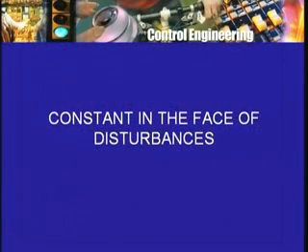So this will remind you of what we talked about earlier, trying to keep something constant irrespective of, or in the face of, disturbances. In this case, the change in the load, the nature of the load itself, the material or the surface which is to be ground. If the grinding speed is kept the same, the torque that is required may be different.